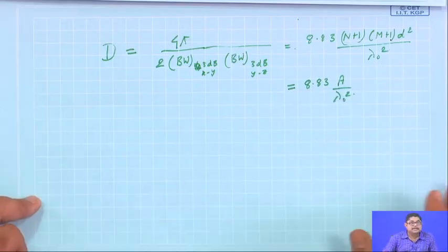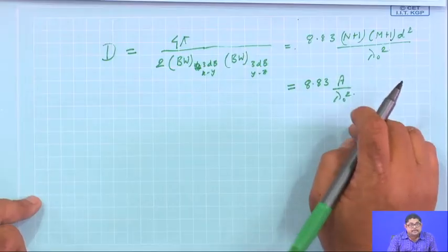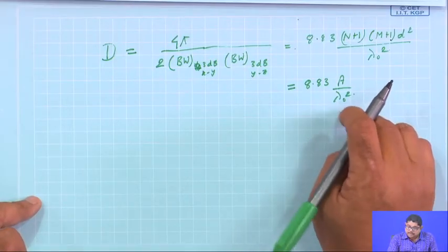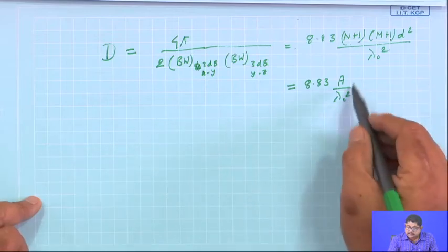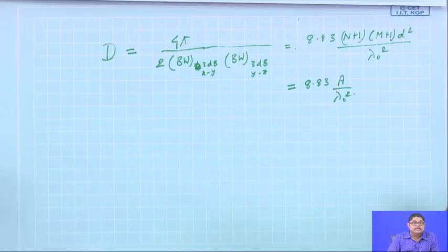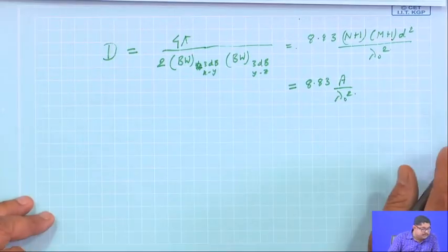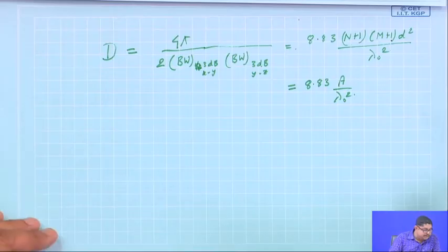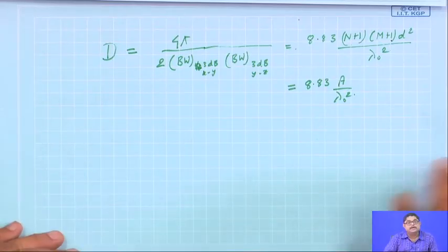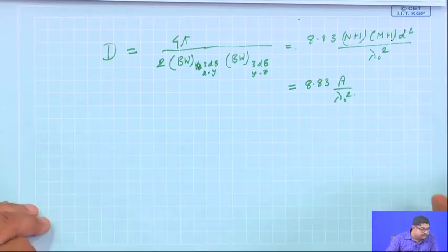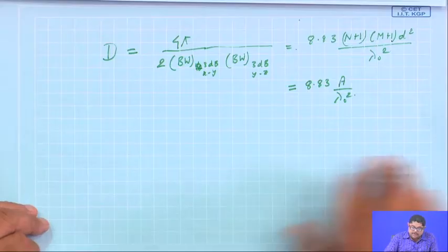The same thing, that physical area in terms of wavelength, that means the electrical area, into some constant term. So, directivity is proportional to the area measured in wavelength squared. This is a general property of area antennas. So, in this case also that came.